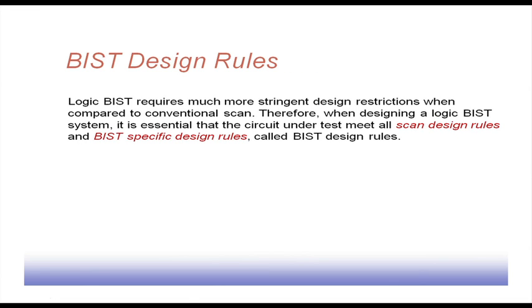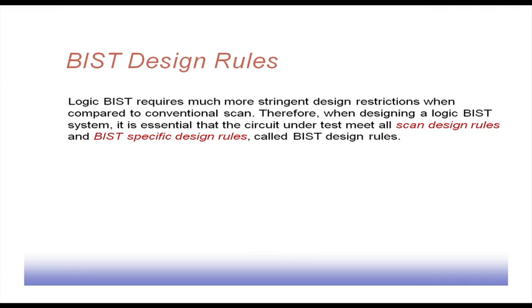BIST design rules: there are certain design rules that must be followed while having this logic BIST. It requires more stringent design restrictions when compared to conventional scan. Therefore, in designing a logic BIST system, it is essential that the circuit under test meet all scan design rules and BIST specific design rules, called BIST design rules.